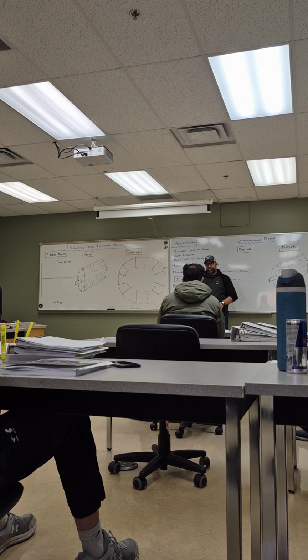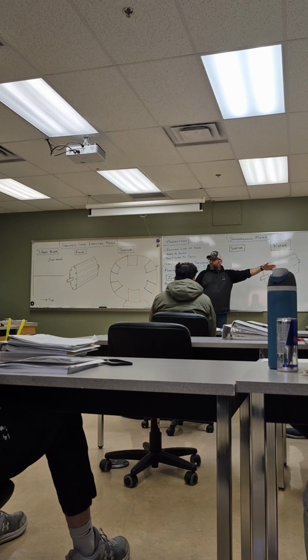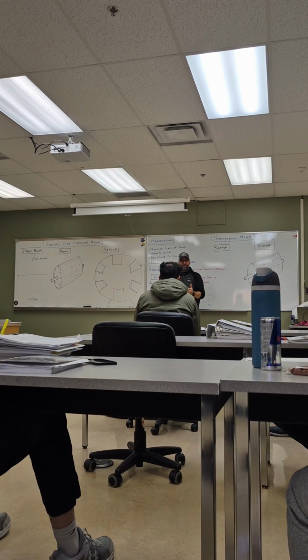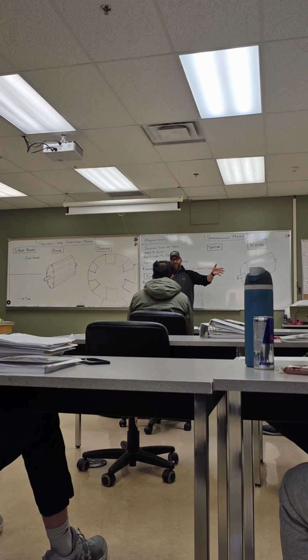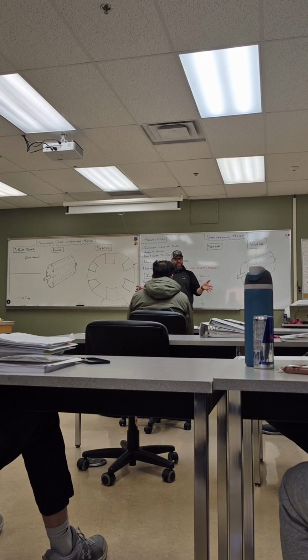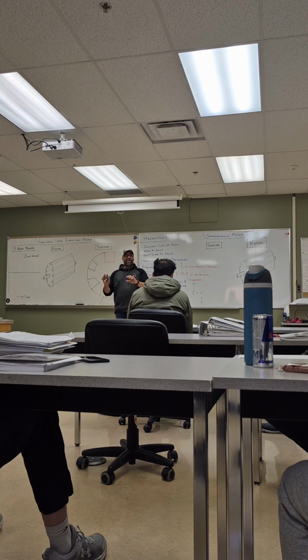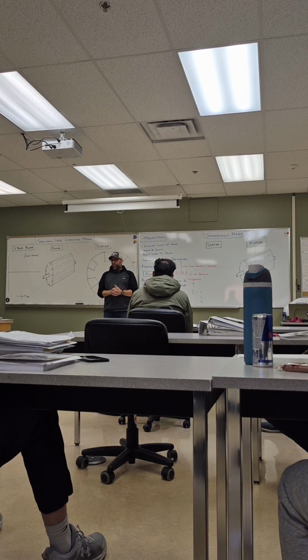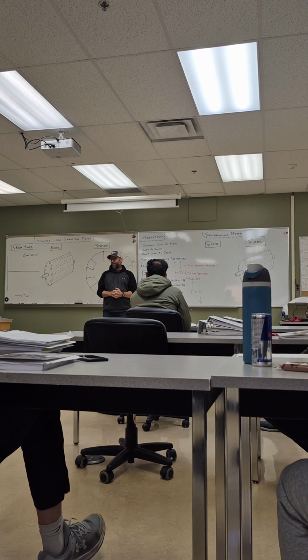We take a transformer and we step voltage up really, really high, so the current's really, really low, and it's the current that equals losses. But we can get a long ways away with really low current, have very minimal losses, and still get a lot of power at the other end. But you can't do that without a transformer. You can't take 500 volts DC and make it 50,000 volts DC, not possible. It is now with our modern electronics, which is really cool, but the cool thing is you can take any AC voltage and make any other AC voltage you wanted easily with a transformer.